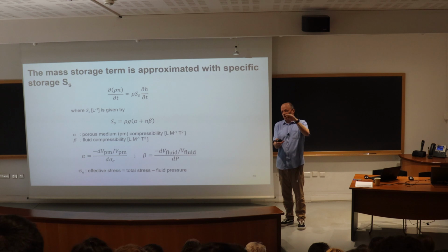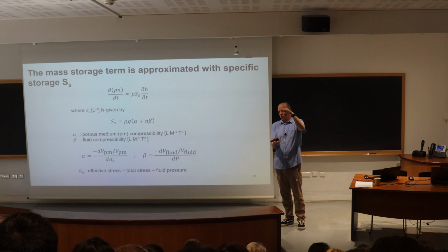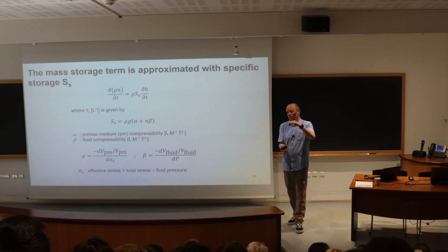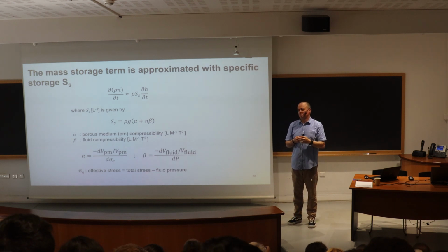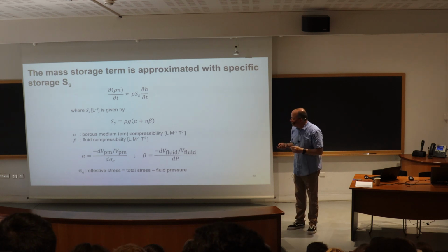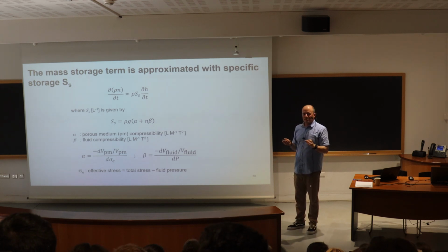There's the same amount of material. So the clay material will start supporting more and more of the weight of everything above, and the clay is super compressible. So that's why you can have tens of meters of compression or subsidence of clay. Is that clear?